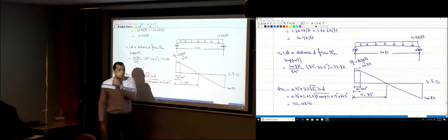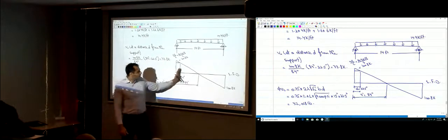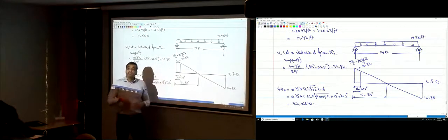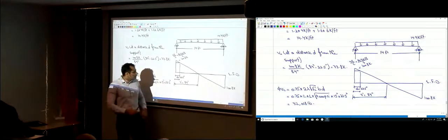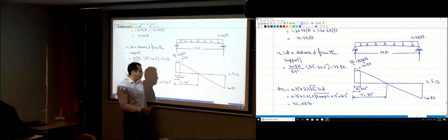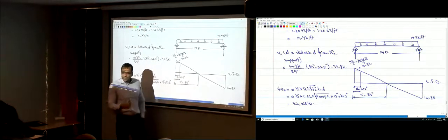So I'm not going to put 5 inches everywhere. As I move, I just need to increase that spacing. Definitely maybe every foot you can change your spacing, find how much the shear is there and change the spacing, but that's not practical.